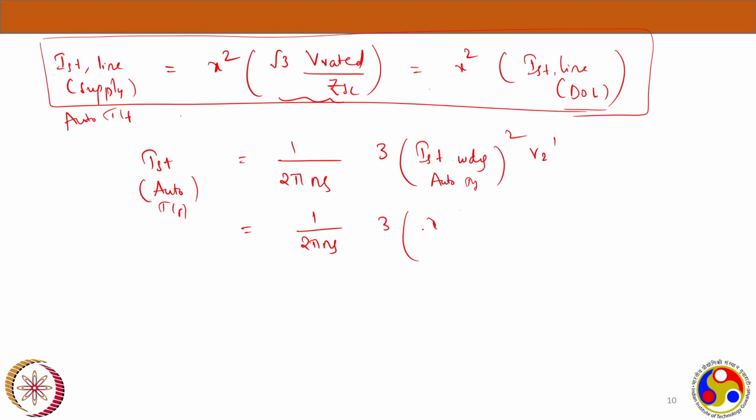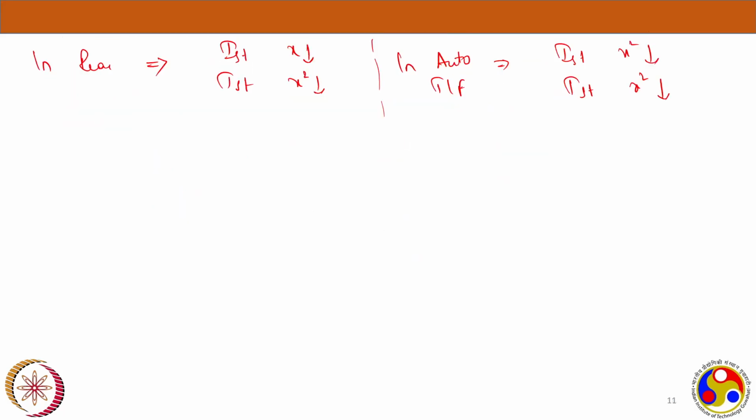But the issue is in both of these starting methods, reactor and also auto transformer, we have to buy these components ourselves. You have to get a three-phase reactor in the reactor starting method, and you have to get a three-phase auto transformer. Getting a three-phase auto transformer is very costly, and you have to put it between the supply and the motor, and then remove it once the motor starts. There's no role for it to play afterwards. It's a very costly affair.